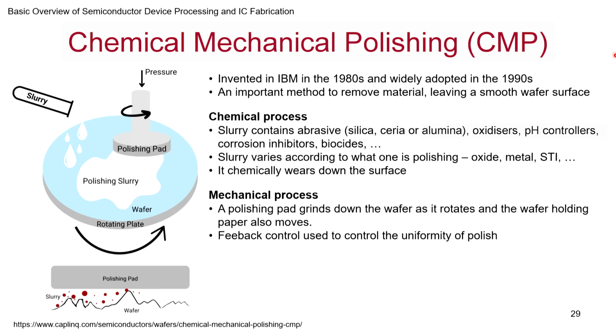And there is, of course, feedback control. Once you have a physical process and it's moving, you can have feedback control to release more slurry or less slurry, and overall you can control the process. And although it seems like a messy process, it can give certainly sub tens of micron and sub nanometer type smoothness. So really good smoothness one can achieve.